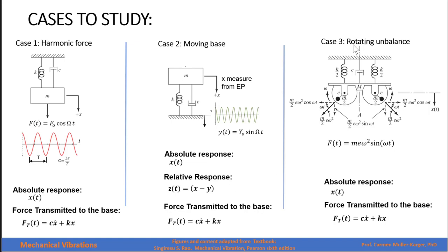The last case will be the rotating unbalance, in which case the vibrating force becomes m e, which is the unbalance, times the rotating frequency of the system squared, times a sinusoidal function. We will find the absolute response and the force transmitted to the base. Let's start with the first case, harmonic force.